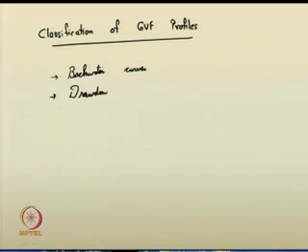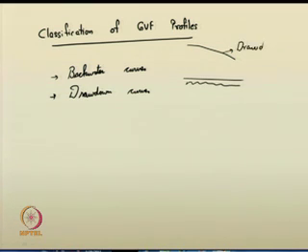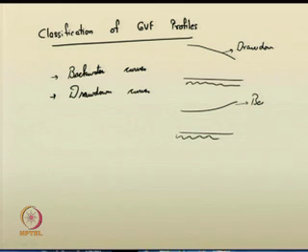If you recall them, we suggested that for any gradually varied flow, if the height of the water surface decreases in the flow direction, then it is called a drawdown curve. If the height of the water increases, then the water surface curve is called a backwater curve, right. So, the same thing, how can you identify now?